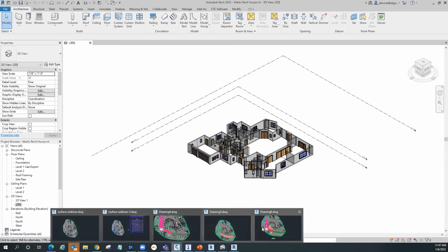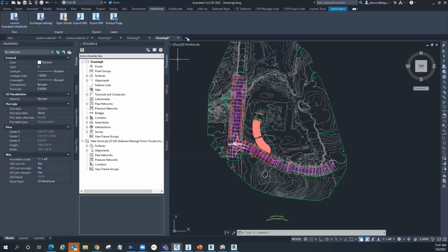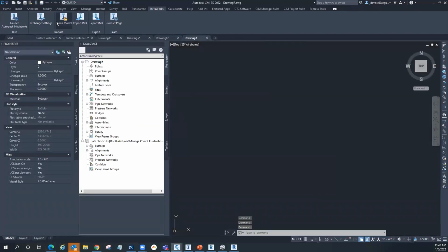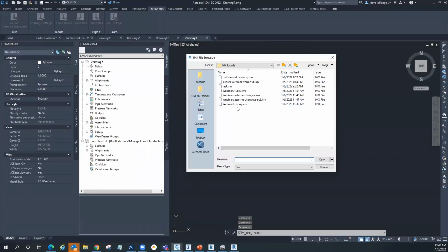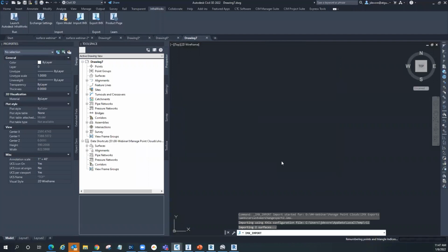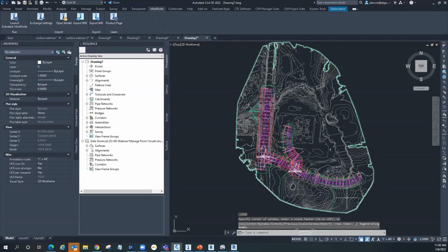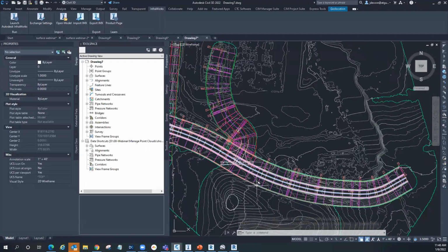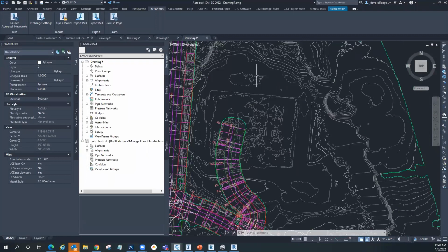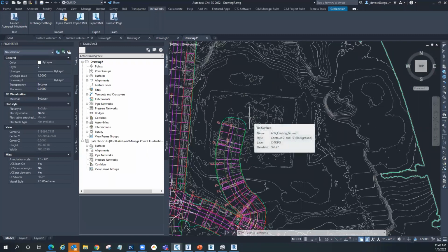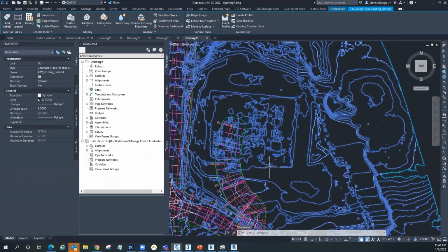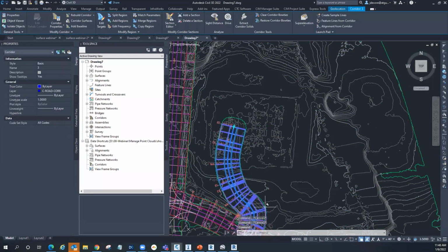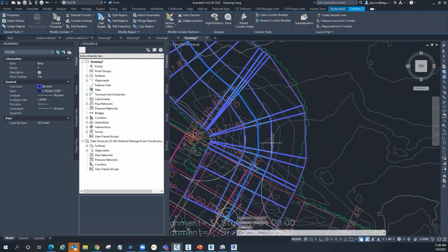But when I bring this into Civil 3D, again, let's do a new drawing to compare for IMX part 2. Because we're bringing it into Civil 3D, Civil 3D is going to only bring in the stuff it cares about. It cares about the grading objects, things like that. But you notice that Revit model did not make it into our Civil 3D drawing. That's fine. The architect is in control of that Revit model. But here we have our component road finally, and we have that grading on there.